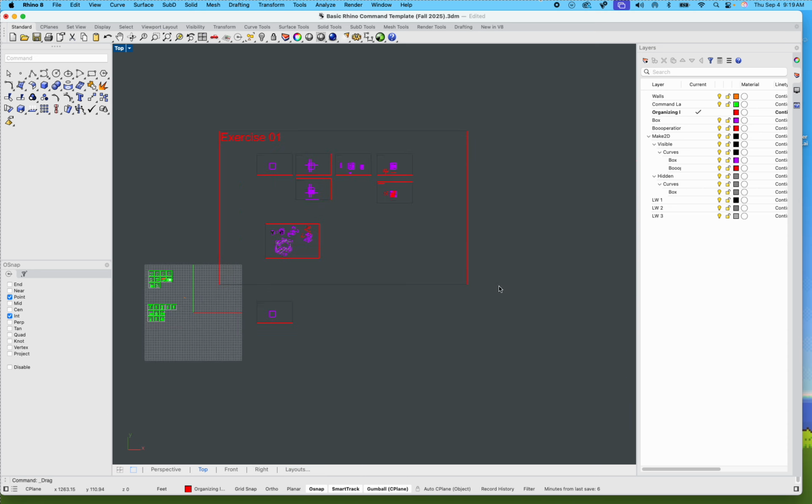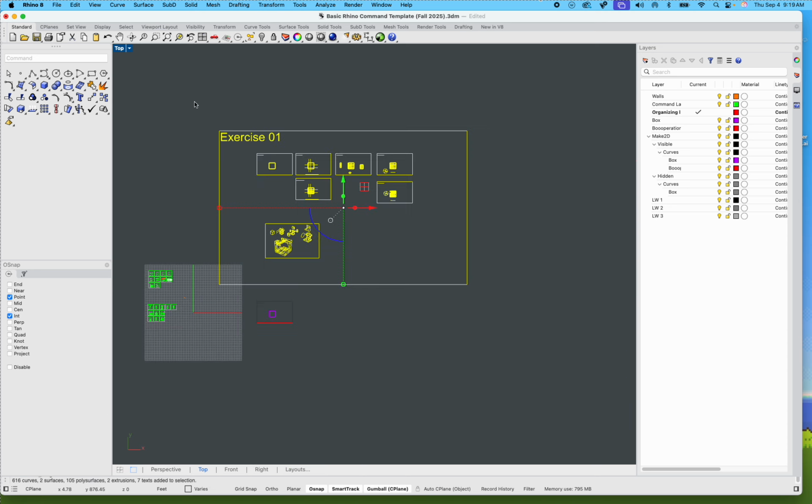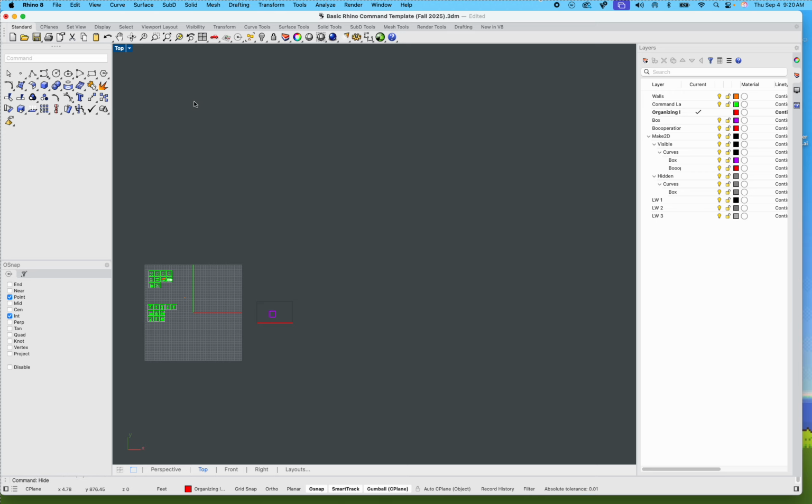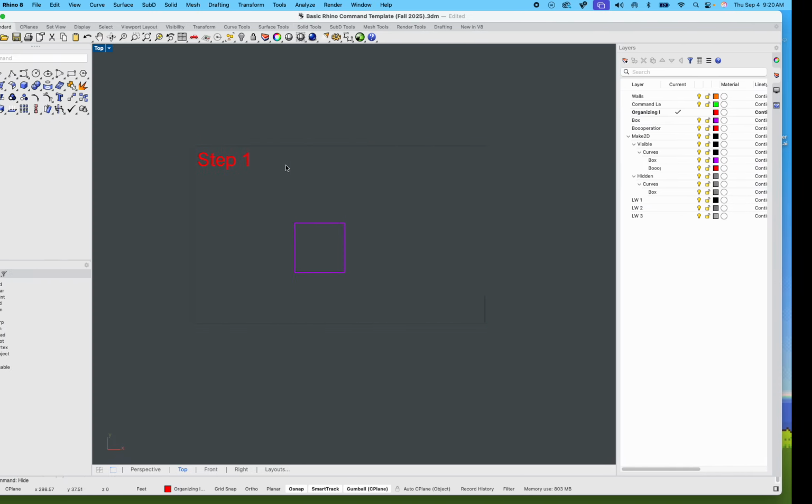Voila, right? Even if that starts to get in the way, another thing that I can do is highlight all of it and type in hide. Get it out of the way. That solves 2 issues, both visually and it actually saves my RAM on my computer, right? So some of you, especially if you've ever designed something in Studio, right, it can get very complex very quick, and the computer is constantly trying to make all of that stuff for you, right? If I hide it, well, it's no longer using the CPU or GPU or RAM in order to create those things. You'll notice once you hide something, it goes a little bit faster, right? And that's definitely intentional. However, we have step 1, 25 by 25 by 25. Got it. Step 2, what do we need?